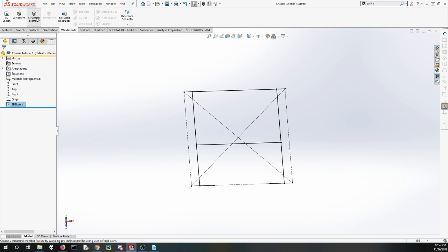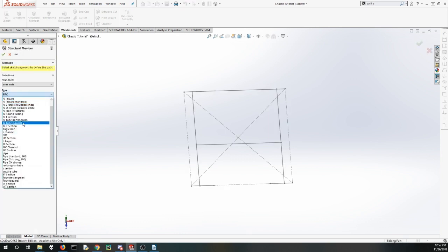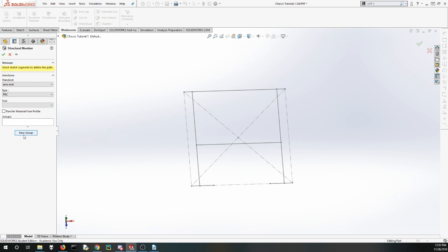I'm going to select structural member, and come here and select FRC, which is the name of the custom tube profile library that I created, which contains several common tube and angle extrusion profiles for FRC, and the files will be linked in the video description.